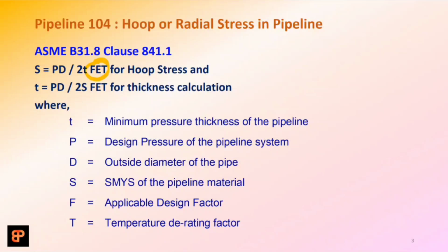So we will not be designing it exactly to the requirement of the design conditions or the applicable loads, but we'll always keep a margin, so that in case of any uncertainty, or any undesired situation where the load exceeds beyond the design value, there should not be any catastrophic failure. So that is the reason for having an applicable design factor.